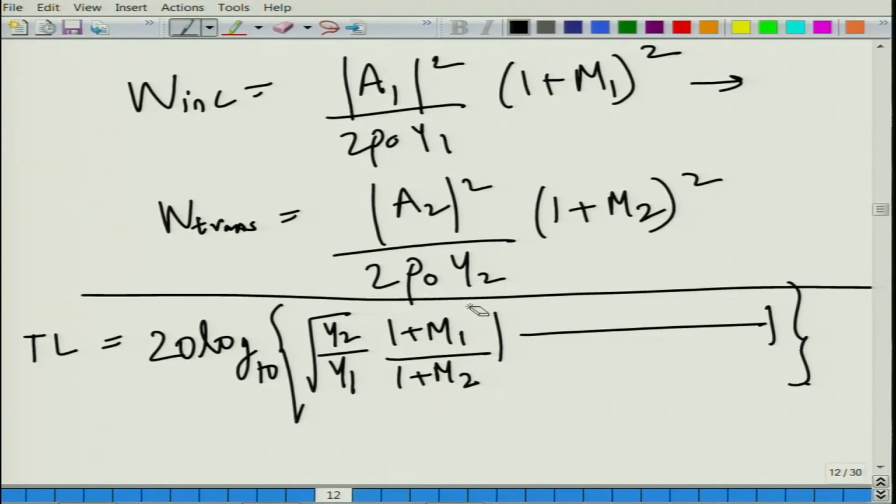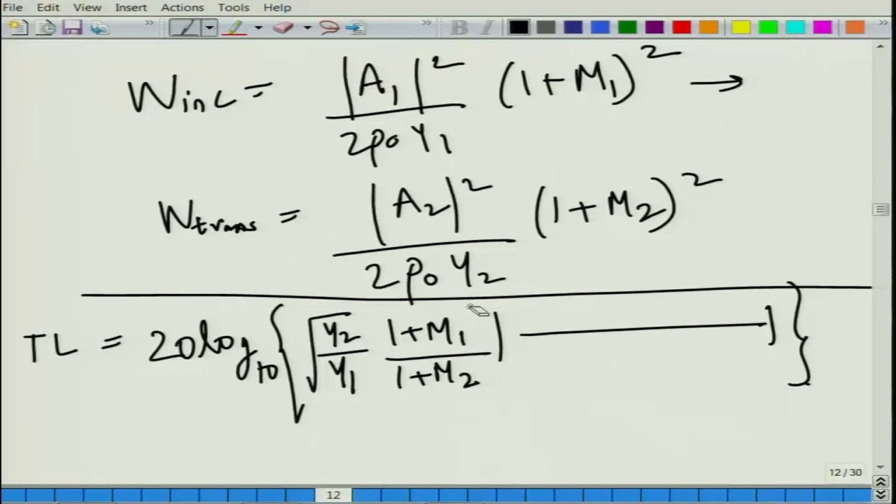If we do some manipulation of the terms, we will see that we can probably relate M dash and J dash in terms of the classical variables, but then you have presence of mean flow Mach number terms, and we will develop again some expression for the acoustic power radiated and carried by the forward moving wave, and that carried by the backward moving wave and all that, and possibly talk about transfer matrices for tubular elements or extended inlet outlet elements, and do all those sort of things.